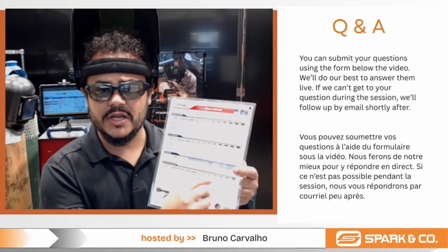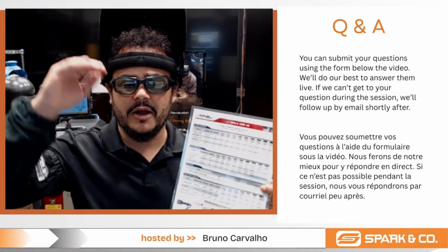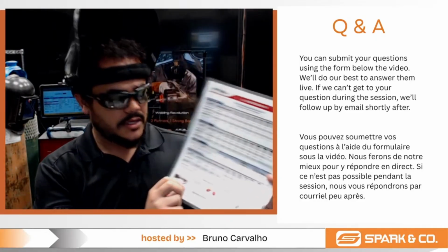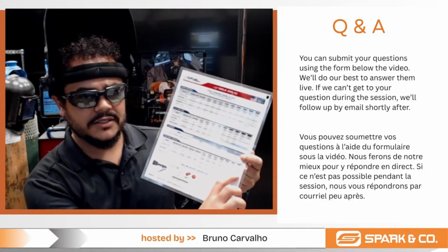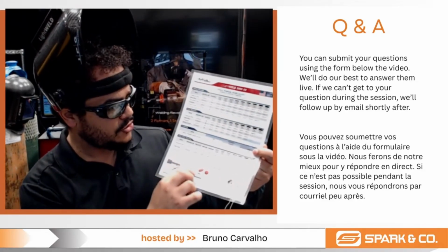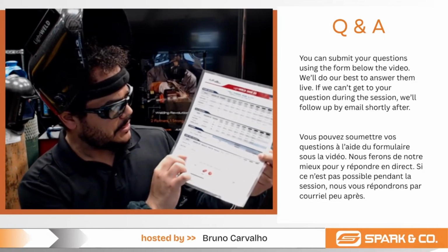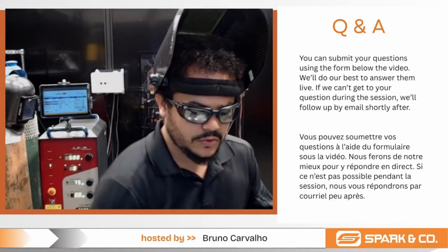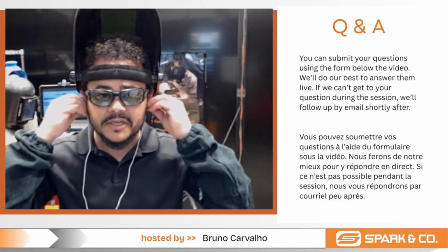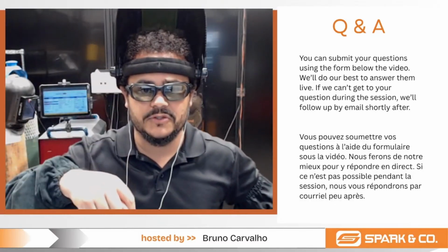when you reach higher wattage, when we require more power, you need to adjust. You have a red dot beside the power, and if you read at the bottom, you need to adjust the frequency. What that means is that the laser is penetrating more with 2000 watts.